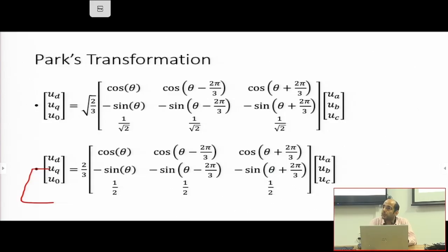So we use a transformation which is called the Park transformation, and we convert AC variables to constant quantities. Okay. So we have two axes now, D and Q axis, which contain the required information of the AC. The information is not lost, otherwise we won't know how much is the AC active or reactive power. We just convert the three-phase time-varying quantities to two-phase DC quantities.